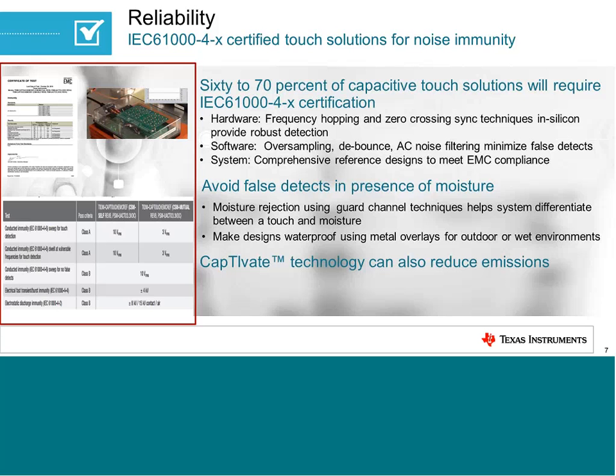In fact, we went and built up a whole system, went to a third-party lab, and got fully qualified for IEC 61000-4-6. There's another test called IEC 61000-4-4, which is for EFT, and we passed it at 4 kilovolts EFT, and IEC 61000-4-2, which is an electrostatic discharge immunity test, which we passed at 8 kilovolts on contact and 15 kilovolts in air. So how do we do it?